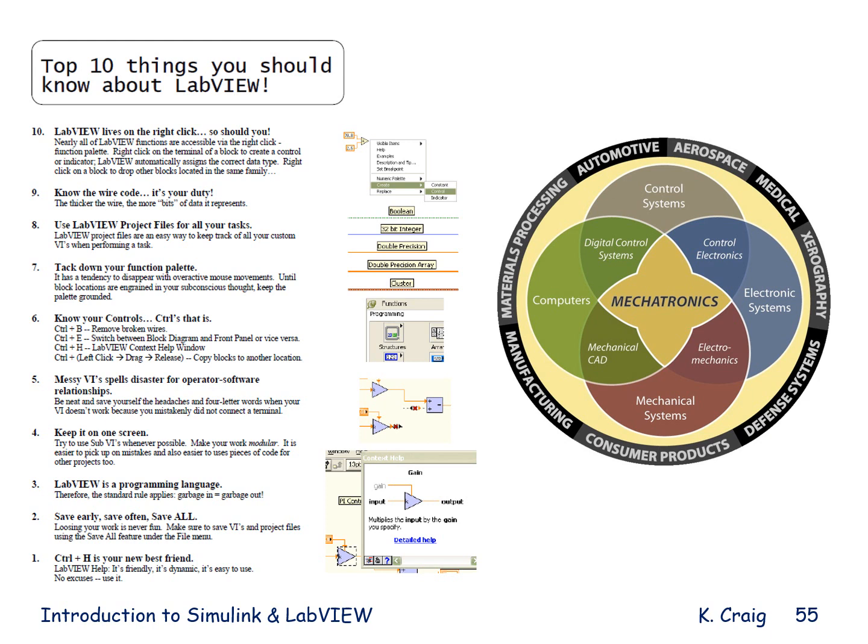Here is a top 10 list. Top 10 things you should know about LabVIEW. You should read these carefully and refer to them often. Number 10, LabVIEW lives on the right click. So should you. Number 9, know the wire code. It's your duty. Number 8, use LabVIEW project files for all your tasks. Number 7, tack down your function palette. Number 6, know your controls. That is the control key plus a letter to perform various functions.